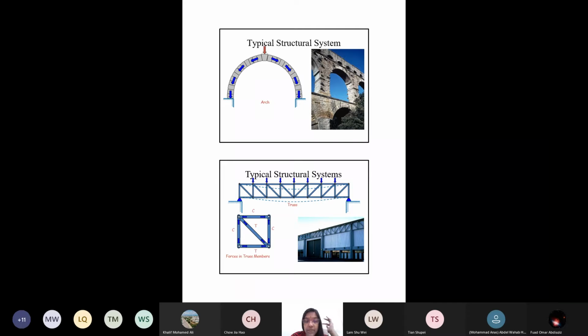You understand what tension and compression are, right? Compression means reduction in length and increase in cross section; tension means increase in length and reduction in cross section. In this situation of loading, what will happen, compression or tension? Must be compression, right? It is going to reduce or get compressed. The overall length, if you measure after application of the load, will be reduced because it is fixed at the end. If not fixed at the end, there is a chance of some flexibility.